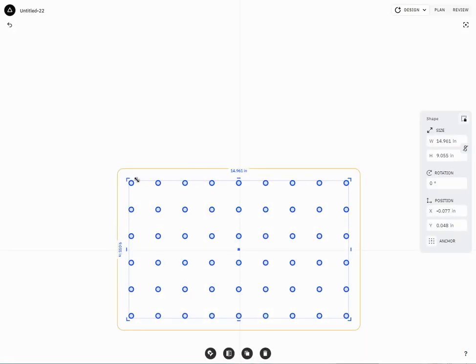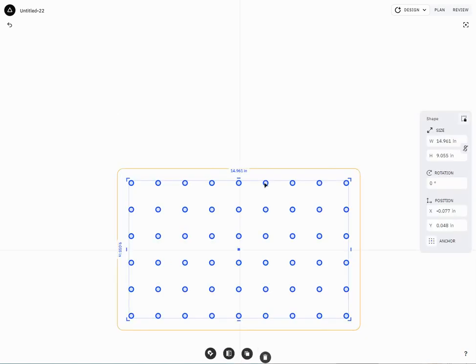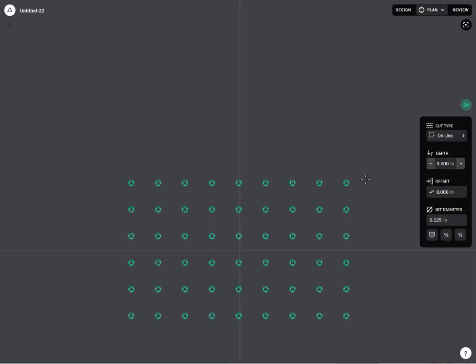So now this is going to present as one object. You'll see if I just select it, it sort of grouped them, but it hasn't made one massive compound shape, which is the key, because it's not cutting holes in a bigger shape. These are two separate shapes. So let's go through. I'm going to start with these and move over to the plan mode. So basically we've cleaned up our DXF, then we can treat these independently.